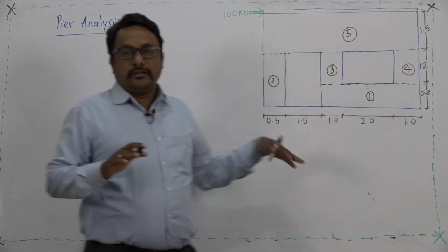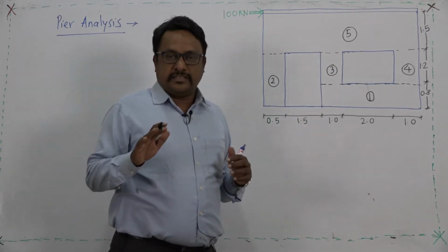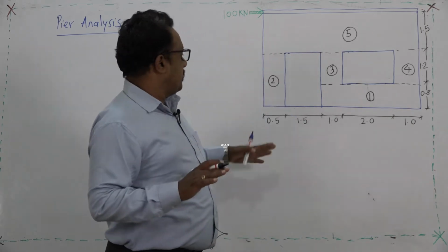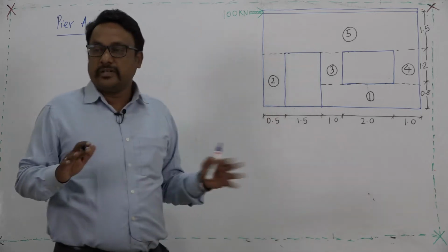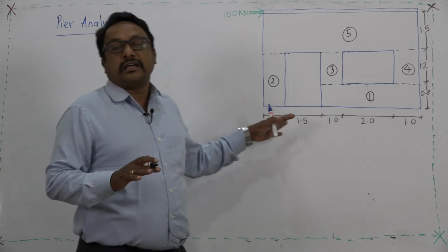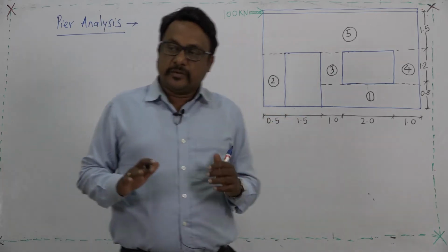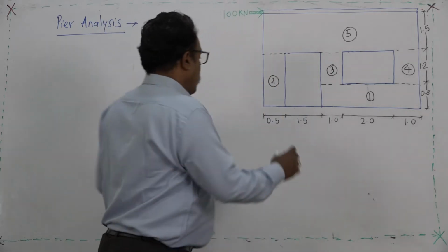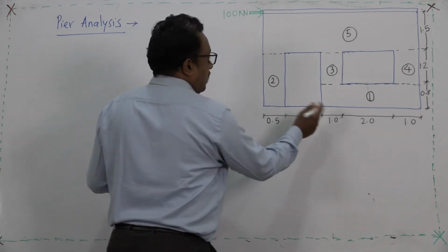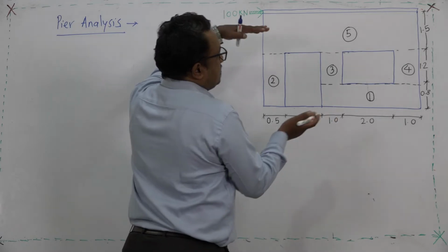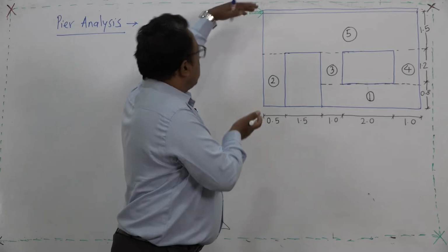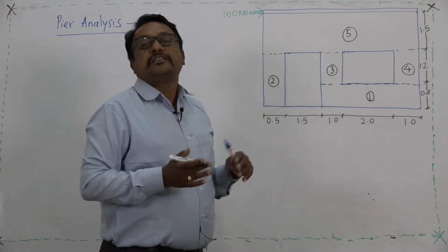Now, let us discuss the methodology available in ASCE 41, and what formulas we are supposed to implement in this analysis. The important task is to work out the stiffness of the wall, generally referred to as K or R. The formula in ASCE 41 depends upon the boundary condition of each pier.